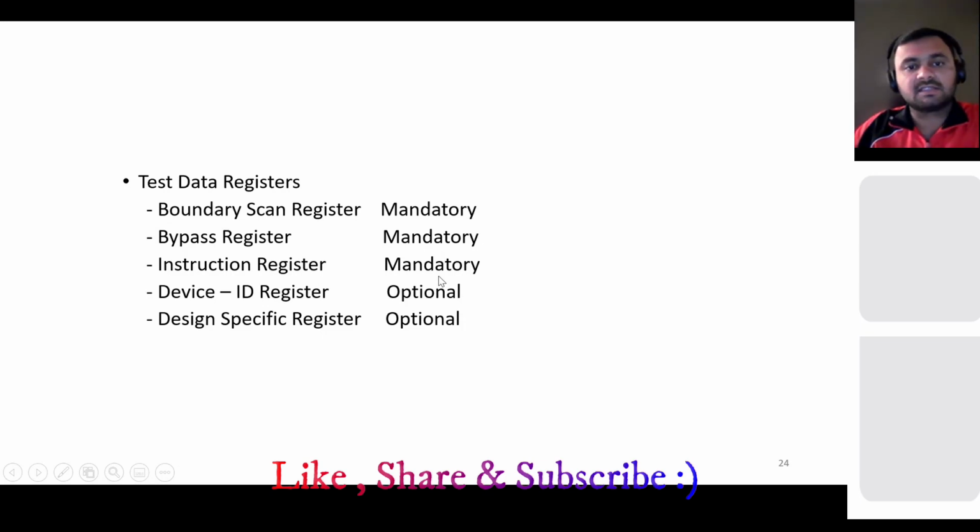And then you have the instruction register. Basically you need the instruction to perform any operation, so that's why it's mandatory. Then you have this device ID. Like you have 10 different ICs from 10 different manufacturers, and you want to identify which device it is. So you can have this device ID register, which is optional, it's not that much required. And then design specific register. Whatever specific ASIC you are designing, based on that you have some design specific register there, which is also optional. These are just 5 for example, but there are many more.